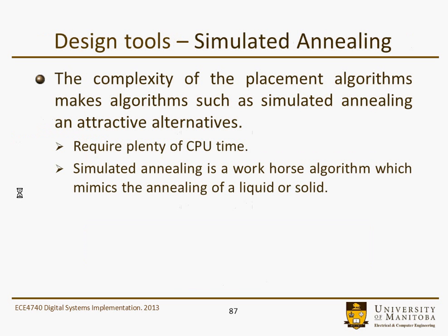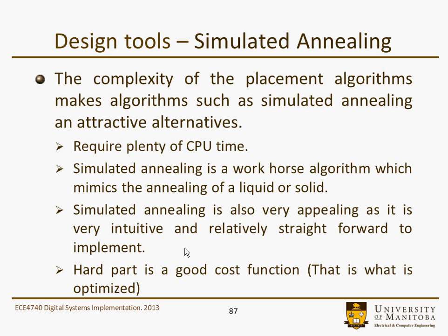I'm going to talk briefly about simulated annealing. The complexity of placement algorithms makes algorithms such as simulated annealing very attractive alternatives. The downside is they do require plenty of CPU time, but it certainly is a workhorse algorithm which mimics the annealing of a liquid or solid. Other algorithms are used, but simulated annealing is certainly one that you should be aware of and be somewhat familiar with. It's very appealing, very intuitive, and straightforward to implement. That's the nice thing about it.